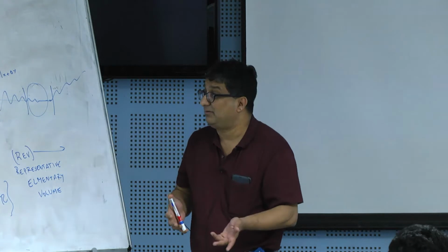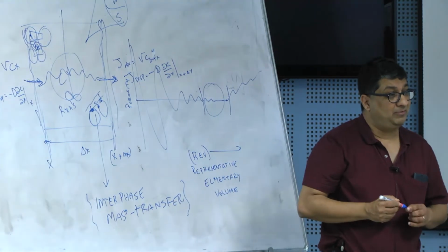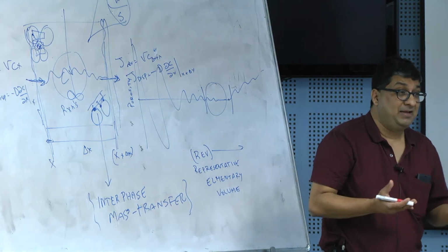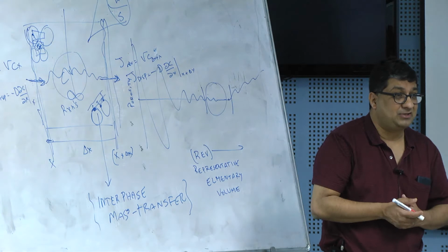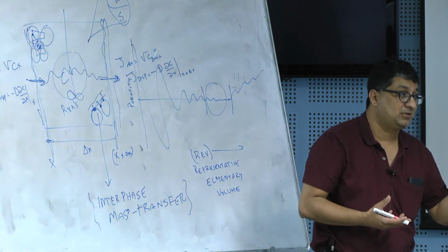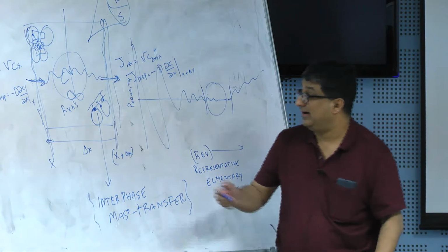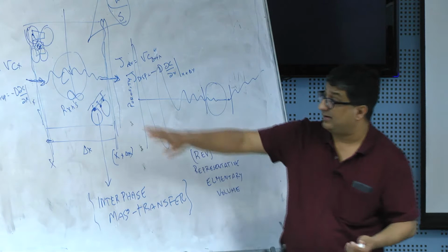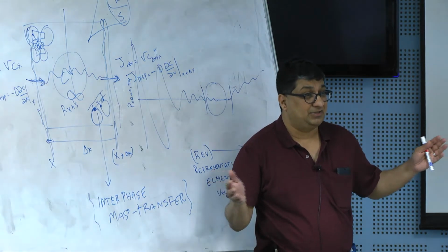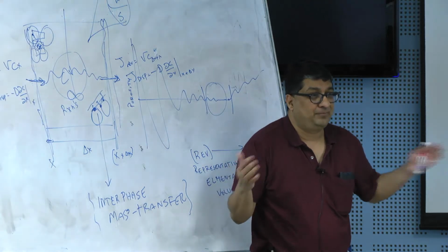The other assumption that we make is that this control volume is well mixed. Remember, we are only taking average properties of what is happening in the control volume. So if I sample anywhere in that control volume, I will see the same concentration in the liquid phase and in the solid phase. That again is not true, it is an assumption, but what we are measuring is an average concentration, not necessarily the real concentration that is there. Given this assumption that our reactor is well mixed, you do not want to make your representative elementary volume very big. If I only had one control volume over the entire aquifer, I would be assuming that it is a well mixed reactor, which obviously is not what it is.